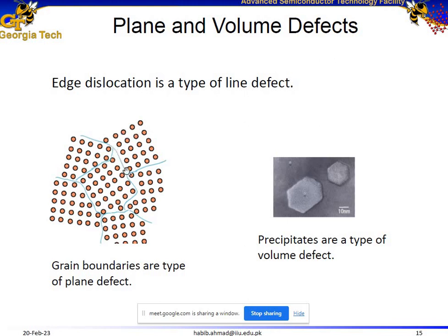because these atoms terminated over here have dangling bonds, and we call them impurities because these dangling bonds introduce a lot of current flowing across the grain boundaries, which deteriorates the performance. If you are using it in diodes, it's going to deteriorate the performance of the diodes. It's not going to give you a perfectly exponential rise in the current versus voltage curve. So these grain boundaries deteriorate the performance of devices.